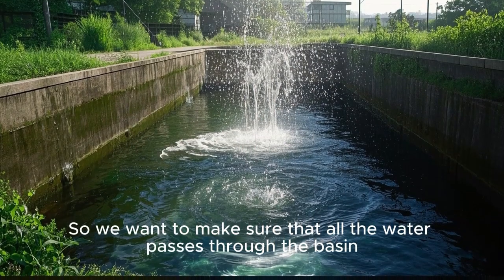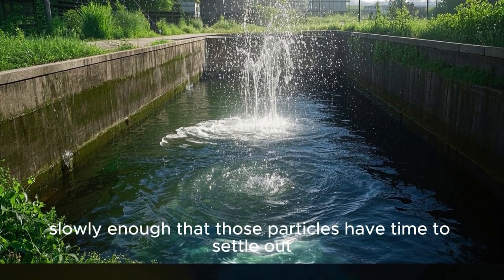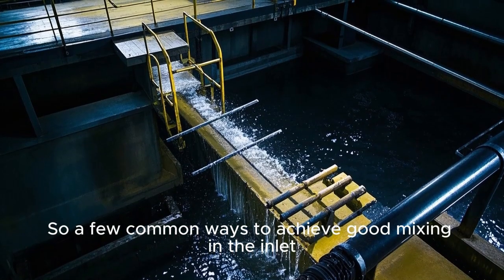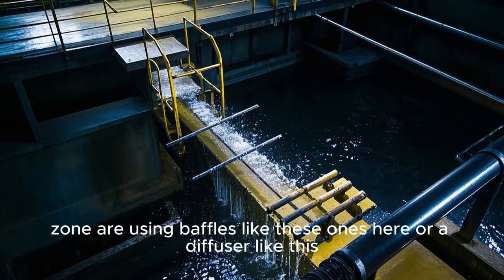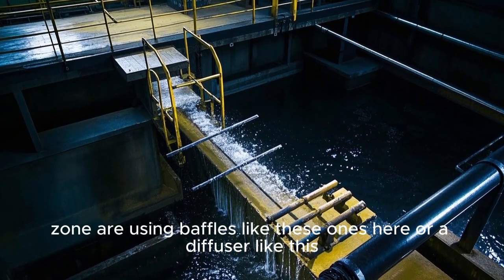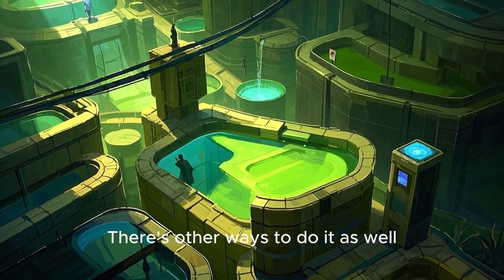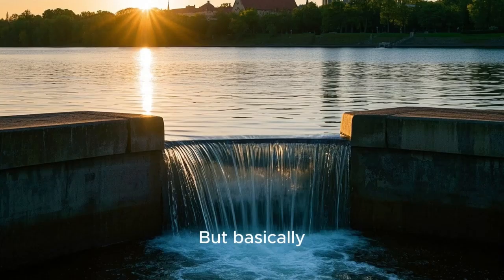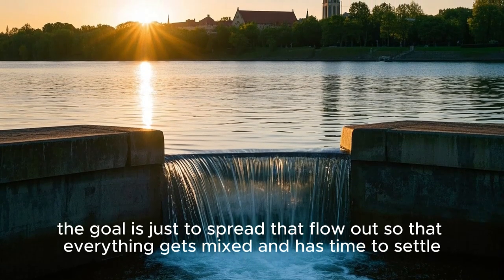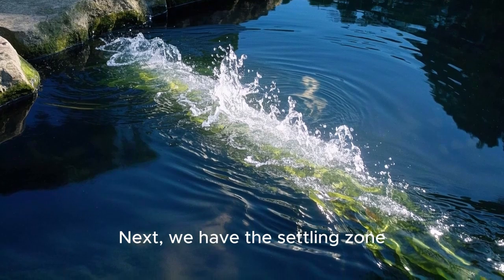So we want to make sure that all the water passes through the basin slowly enough that those particles have time to settle out. So a few common ways to achieve good mixing in the inlet zone are using baffles, like these ones here, or a diffuser like this. These are just a few examples. There's other ways to do it as well. But basically, the goal is just to spread that flow out so that everything gets mixed and has time to settle.